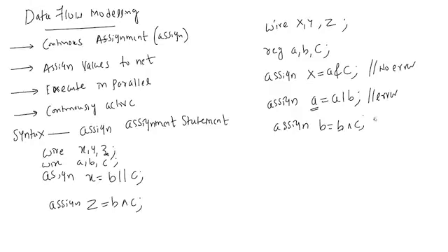Here also you will get an error. Why? Because whatever the b value is, you declared it on the LHS side, and that is actually a reg data type. So remember, whatever variables you have on the left hand side should be wire data type when you are using the continuous assignment statement.